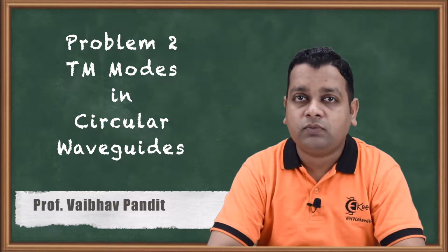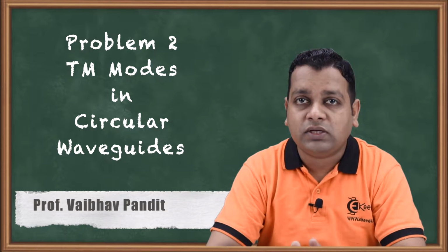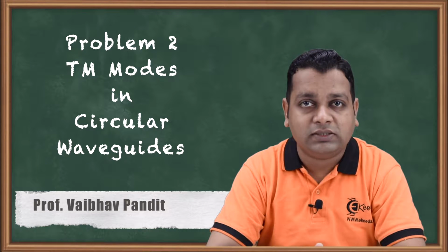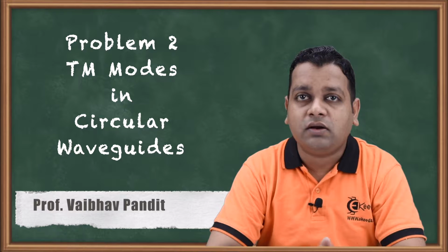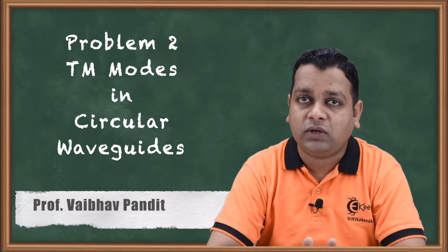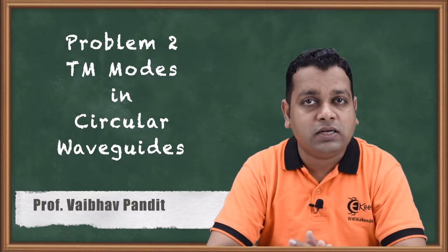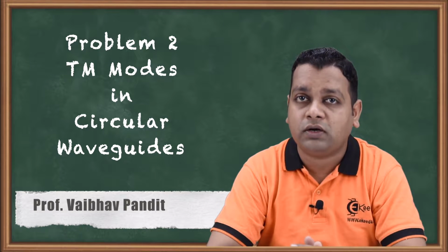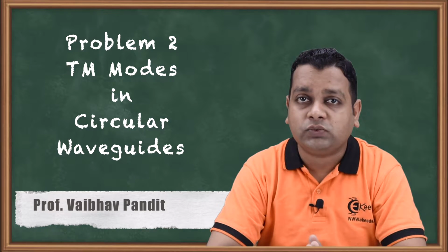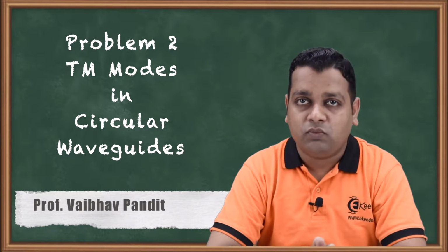We started this chapter first of all to analyze and see in detail what exactly the conventional coaxial transmission line is, and a modification, by preventing the central conductor in the structure, we have a circular waveguide having a hollow cavity inside it. So as we know that the TEM transverse electromagnetic mode is not supported, we have two alternatives, either to go with the transverse electric TE mode or the transverse magnetic TM mode.